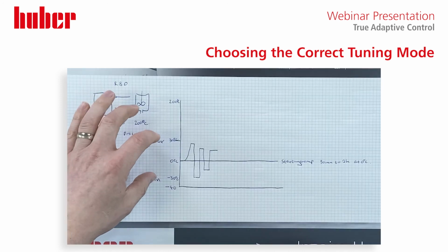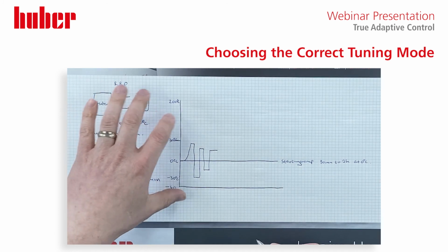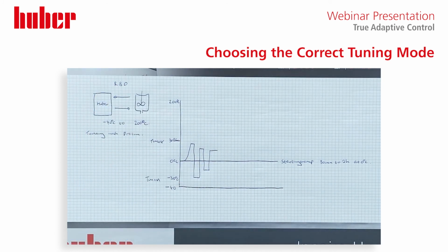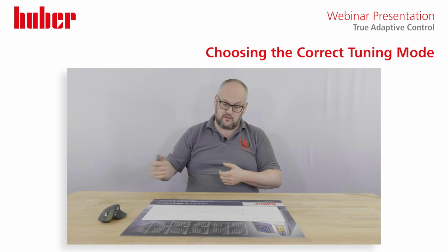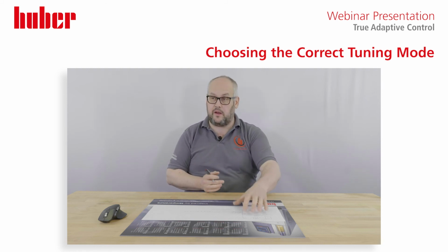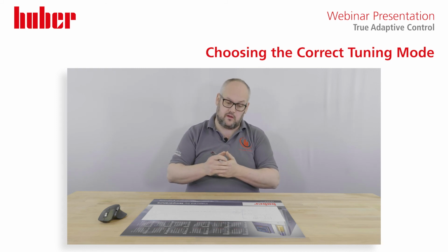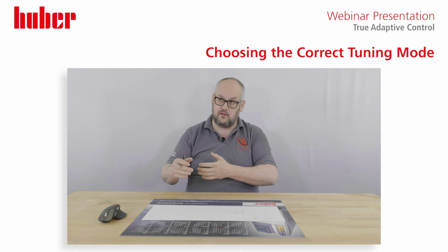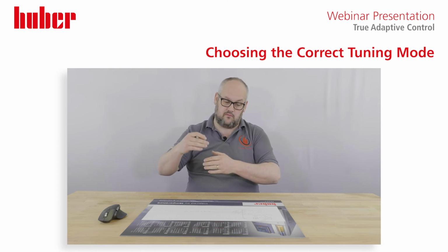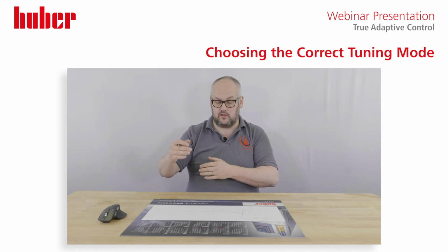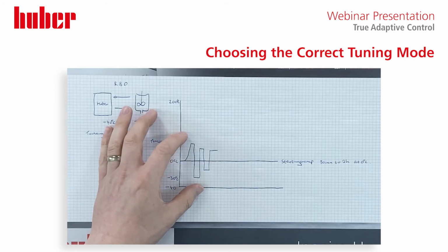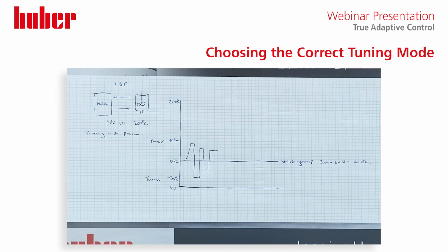This kind of zone between 30 and minus 30 we find very useful on large Unistats, say 900 series, which typically work at minus 80. This often gives better results across a wider range of temperatures than just doing it at minus 50 to minus 80 and minus 50 to minus 20 degrees C, because we're getting the maximum cooling power out of the unit here.